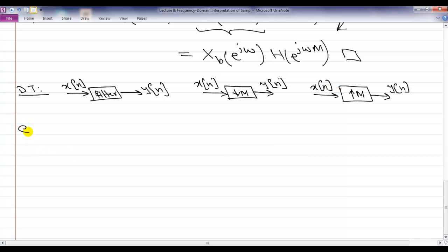We have done the same in continuous time, except for a couple of things. In continuous time, we haven't set up the relationship between the continuous time frequencies and the discrete time frequencies. That's the only remaining piece. For example, if I am given a continuous signal x(t) and I sample it every T seconds, I get x[n]. What is the relationship between the frequencies of x[n]?